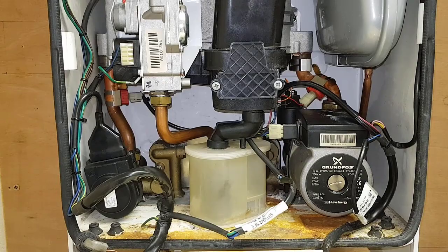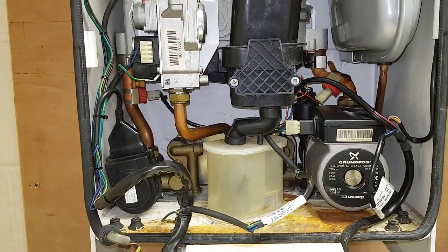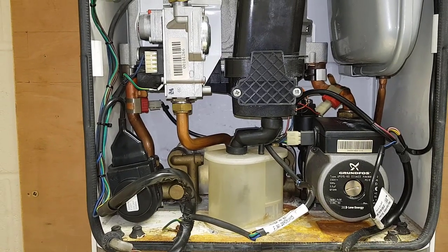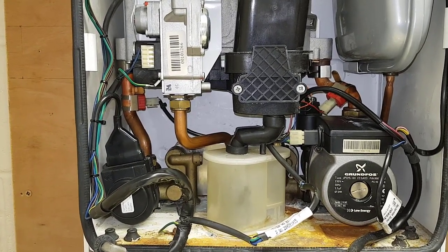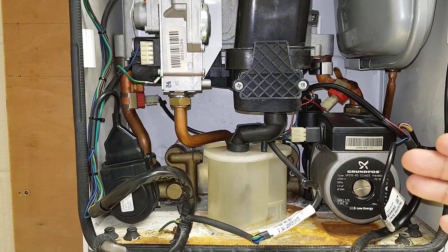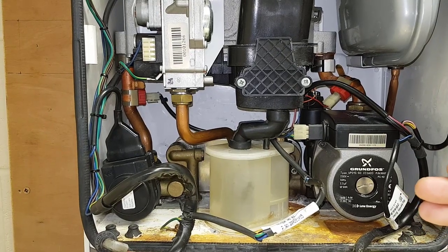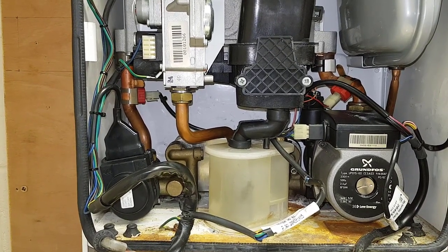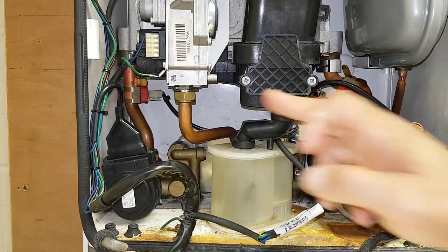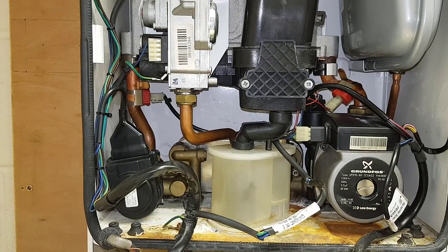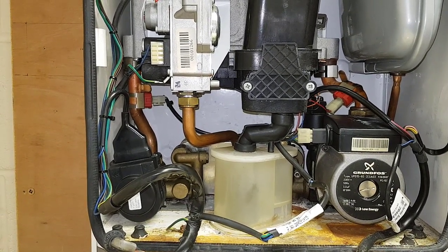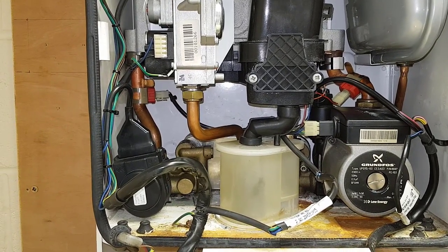Right, so what we're going to do now, I want you to just read me out the rest of the quadrant on the central heating so other people can hear what they are. Right, as you mentioned, we just spoke about the diverter valve, and then we'll check the actuator motor, and then we'll also test the thermistors, which are on both sides. The PCB, which we've kind of mentioned, and then we'll also check the pump.